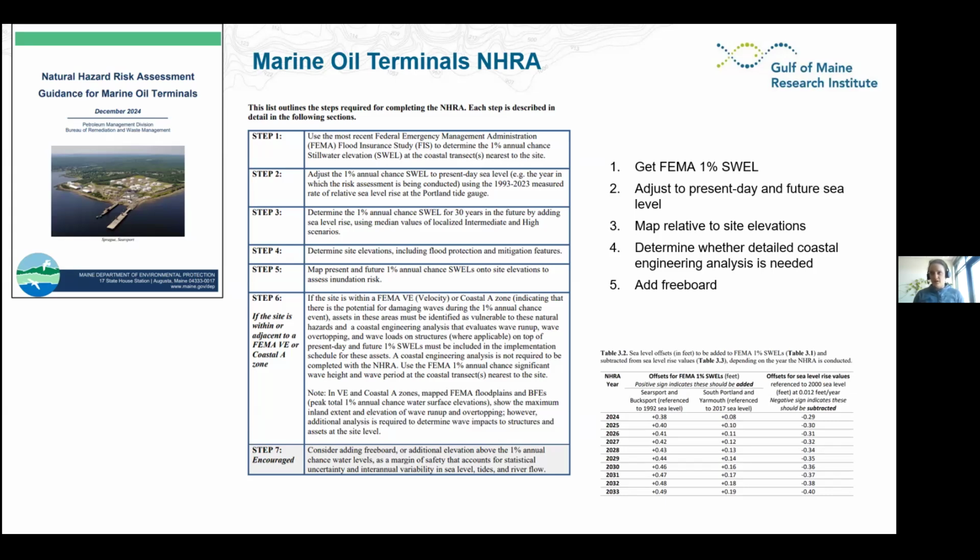a detailed coastal engineering analysis is needed to determine wave loads on structures, and then add freeboard that accounts for all of the uncertainties that come with linear superposition of water levels like this and is in line with local shoreland zoning requirements.